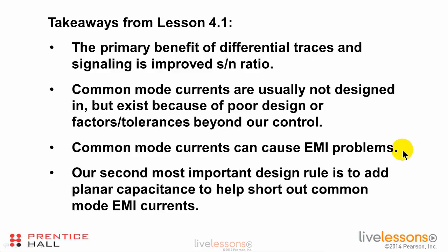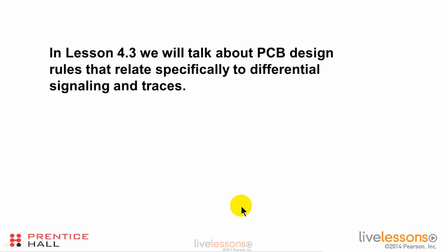Common mode currents can cause EMI problems, and in fact, I've heard experts say that probably 80 to 90% of EMI is caused by common mode currents, not by differential currents. And our second most important design rule is to add planar capacitance to help short out these common mode currents.